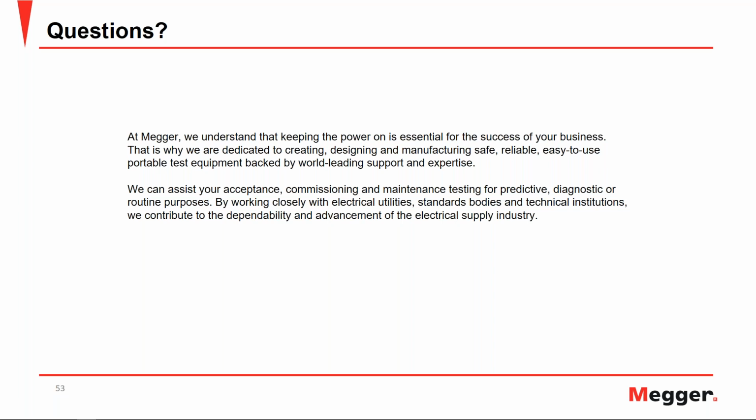Coming back to the question, what is the probable reason for getting negative tan delta value? If you go back and look at the theory of power factor testing, the best power factor that you can hope for is 0. So anytime you get a negative power factor value, it's an indication that something is not right.